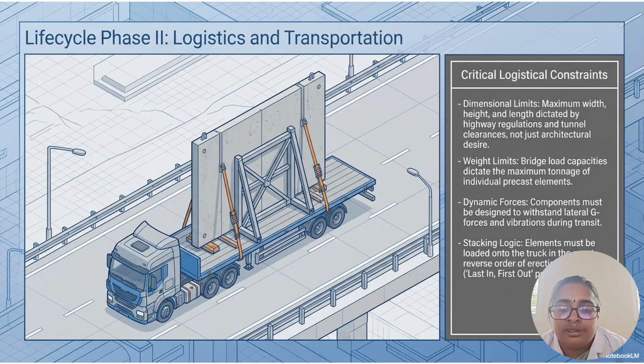And next one is stacking logic. Elements must be loaded onto the truck in the reverse order of erection, that is last in, first out, so that it will be easy for placing the component.